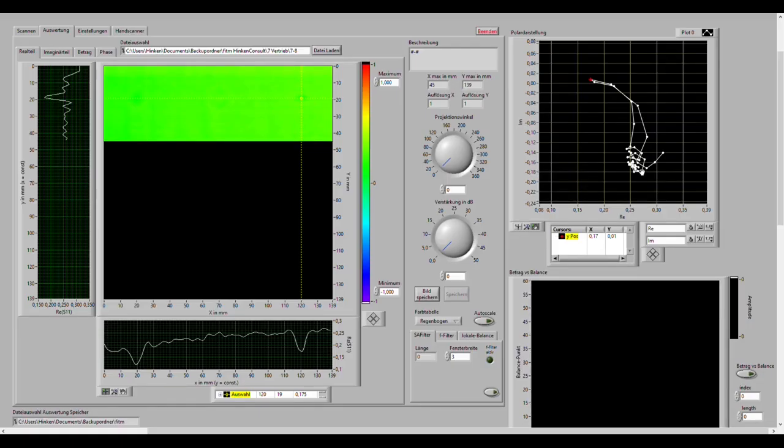This non-zero origin shows the microwave reflection on a location where there is no defect. It results especially from the reflection from the plate's surface and bottom and is the same across the whole plate. A transformation of the data is suitable so that this origin point coincides with the 0 point in the plane. Let me show what I mean.